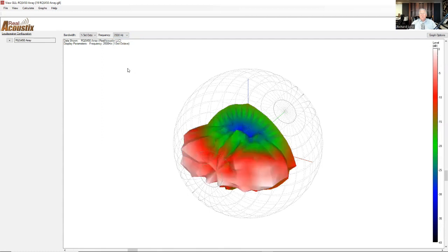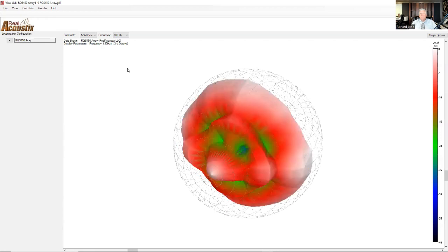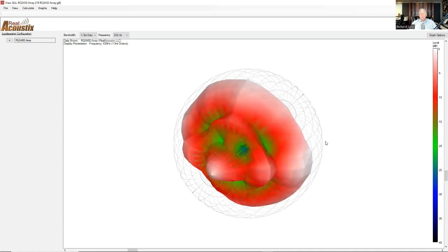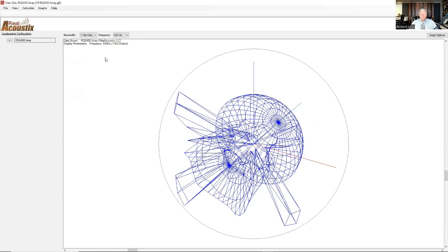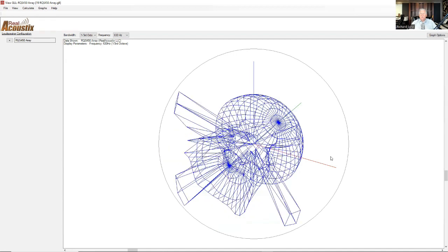Where it becomes very interesting is to understand the difference between diffusion and scattering. So we go back down into these ranges. I'm going to go back down to the 630 where we have strictly a specular reflection. I'm going to change the graph. In this case, I'm going to look at a phase balloon. So when we look at phase balloons, you can see here these big, what we call flowers in a sense, with this type of look, this is specular reflections, and you can tell what a specular reflection looks like.